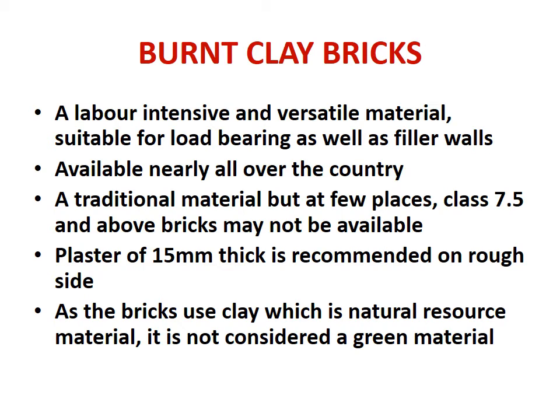But at a few places, class 7.5 and above bricks may not be available because of the soil available there. So that is a problem, that at some places even class 50 or 75 bricks, what we call class 5 or 7.5 MPa, are not available. So one has to find an alternate material. So there is an additional problem.